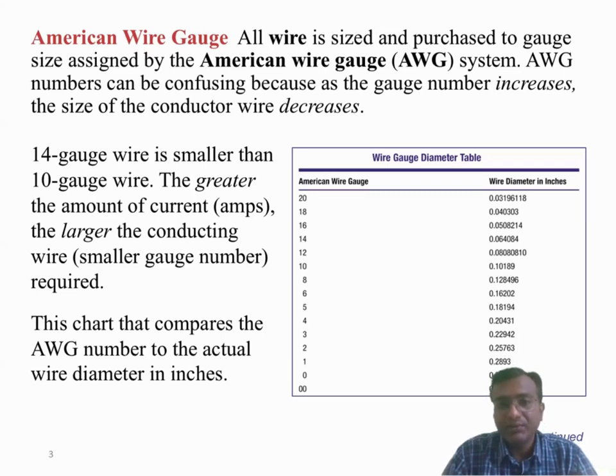For instance, a 14 gauge wire is thinner than a 10 gauge wire. And as you know, for higher current flow you need a thicker wire, which has a low gauge number. Take a small example: a thick 10 gauge wire might be needed to safely carry power to a car's headlight, but a thin 20 gauge wire would work well for connecting small speaker wires.